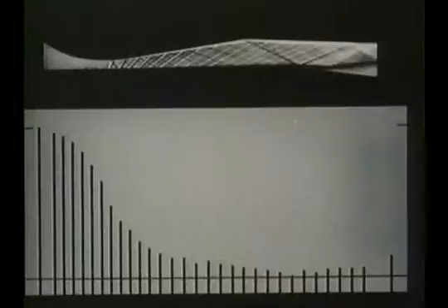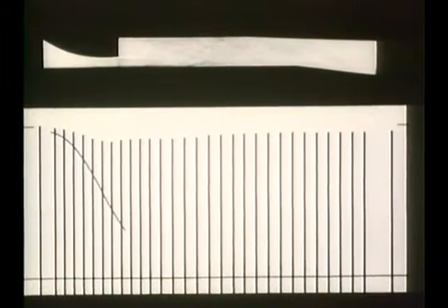When the channel is choked, and we change the downstream pressure with our control valve, we move the shock wave, but there is no other influence on the upstream flow. Because the area, pressure, velocity, and density are all fixed at the throat, so is the mass flow. We can think of a choked channel as a device for maintaining a specified mass flow from a reservoir at constant pressure and temperature. Even if we cut away the wall at some point after the throat, we don't change the mass flow in a choked channel.